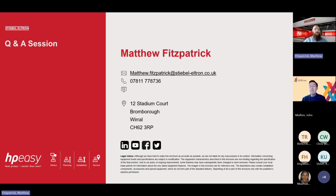Joanne, you are completely correct. I like the expression robbing Peter to pay Paul. Any time you were to add a plate heat exchanger or another transfer station, as I call it, onto a system, you are effectively adding an additional heat loss or inefficiency into that system.